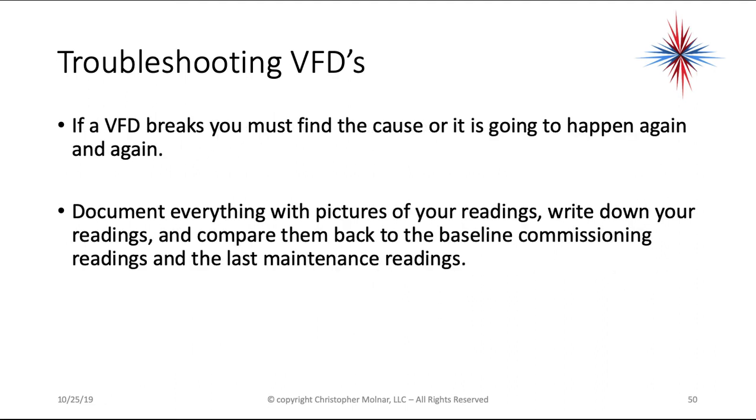If a VFD breaks, you must find the cause or it's going to happen again and again. A VFD sometimes having a problem is a sign of other failures. Document everything with pictures of your readings, write down your readings so you're able to compare them to the baseline commissioning readings or the last maintenance readings.